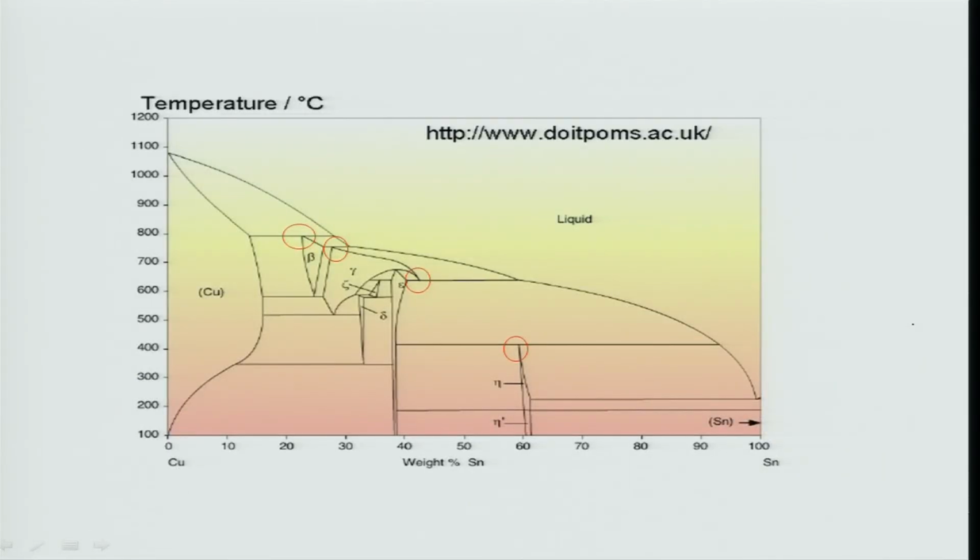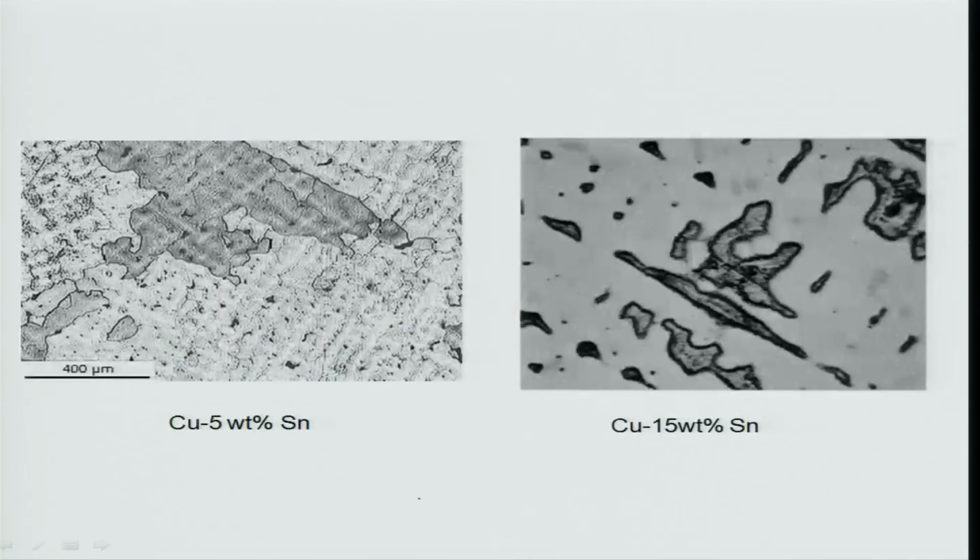Similarly for the copper tin system, which is basically a bronze, you can have peritectic reactions, several of them, 1, 2, 3, 4 are shown here at different temperatures. So beta bronze or epsilon bronze or eta bronze are all produced by different peritectic reactions. And just to show you a microstructure of that, this is your alpha beta bronze, with 15% tin.